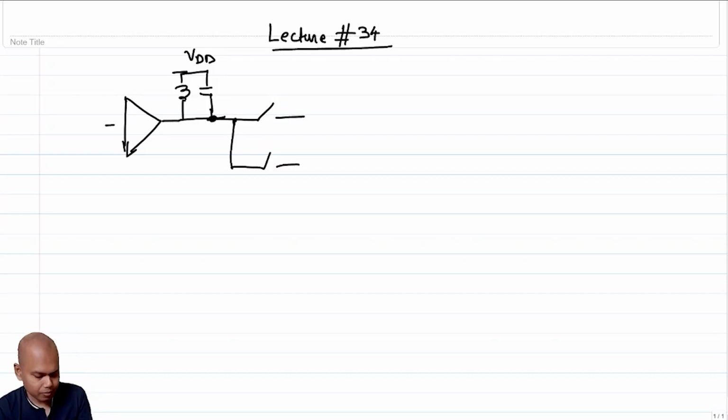By the way, when we are talking about passive mixers here, the idea is there need not necessarily be a DC current through the mixer. What we are interested in is passing the input signal at RF and not necessarily at DC, right?